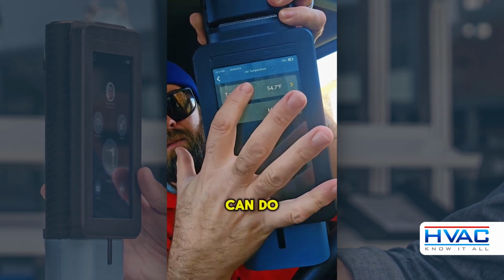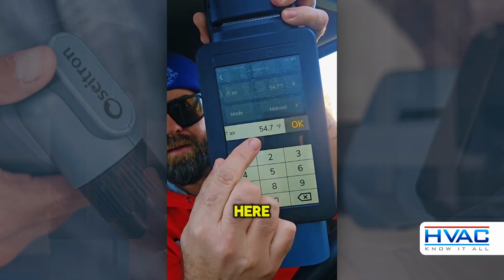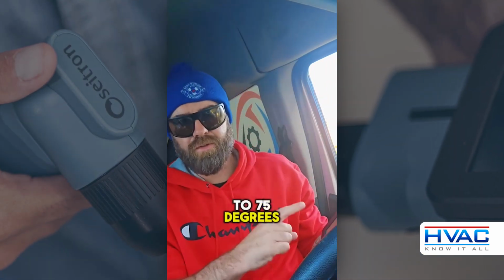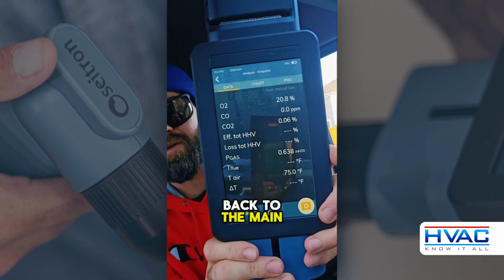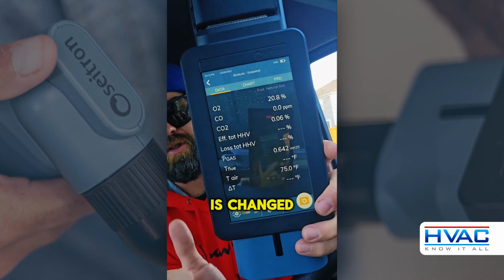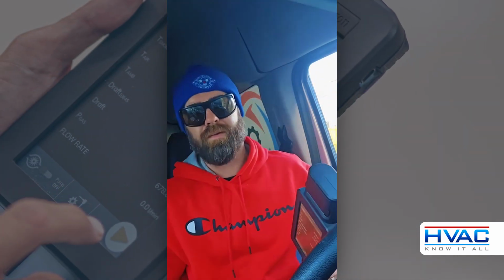And now what we can do is take the temperature of the air outside and enter it in here. I'm going to change it to 75 degrees so you can see what happens. So now it's 75 degrees. Now we're back to the main screen, and you can see that our T air is changed to 75 degrees. Now we're going to get our correct combustion efficiency.